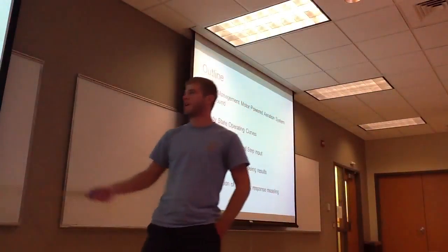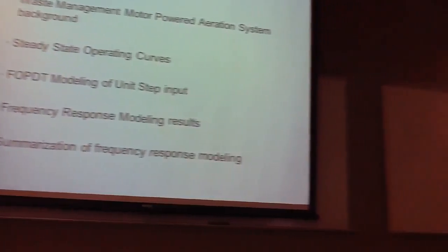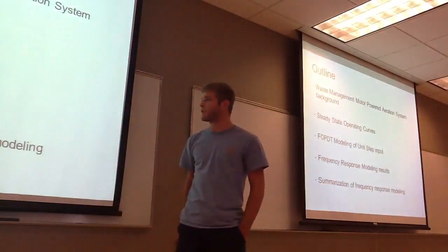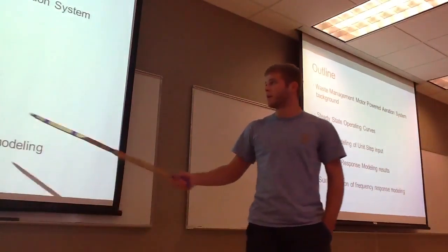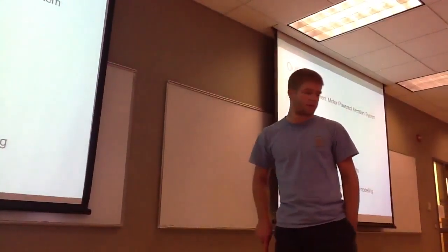Just to give a brief outline, I'm not going to repeat myself too much for all of you, but our whole speed station is based off of the waste management motor-powered aeration system in Chattanooga. Today I'm going to go over our past experiments with steady-state operating curves and the FOPDT modeling of unit step, and the same thing with the frequency response